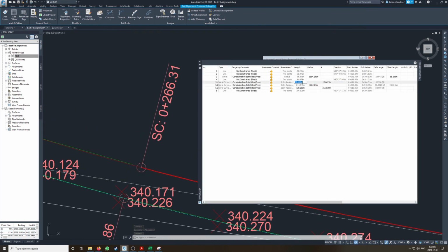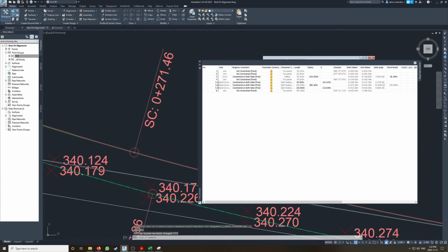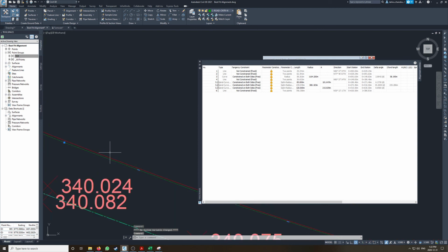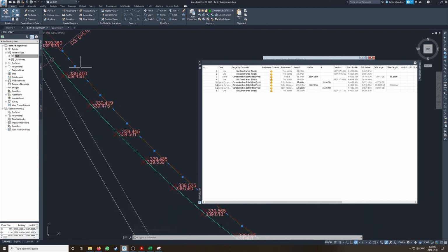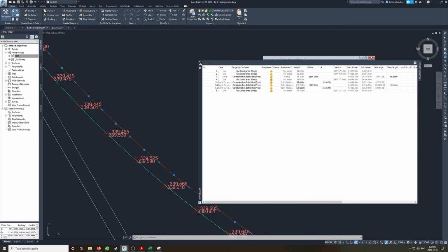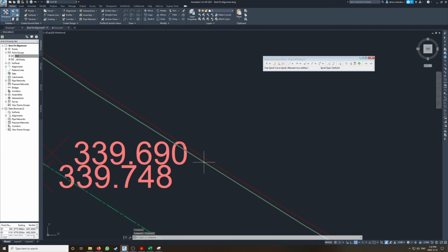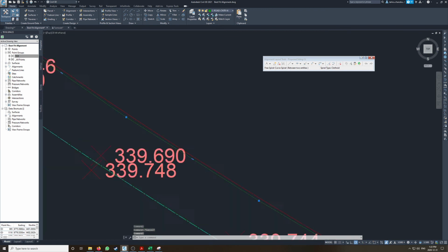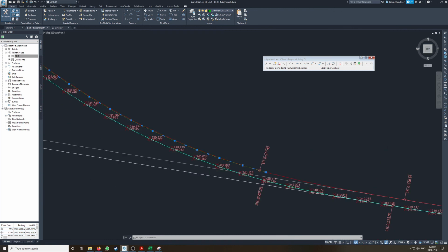Let's try going to 90. 90 is good. Might be a little bit too big. Okay. Yeah, there we go. So we are good everywhere. Yep, this is good. So now your track center is at least 4.8 meters in this. That's what this green line tells us. So therefore, we're not fouling the track.